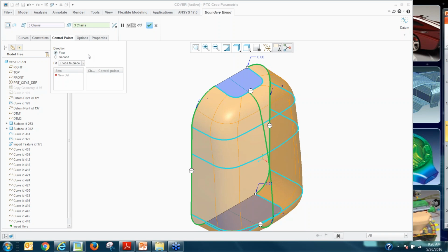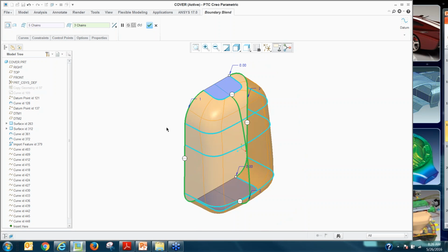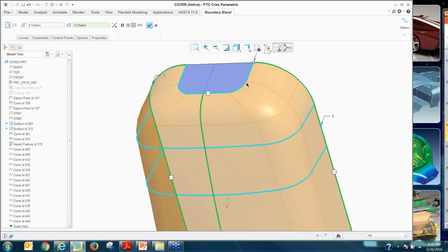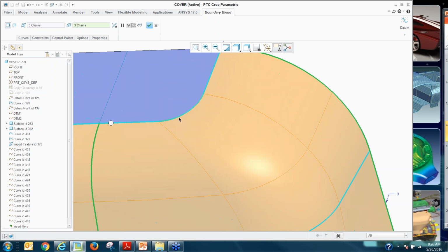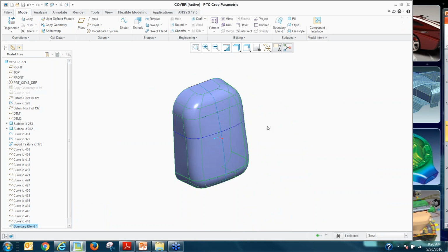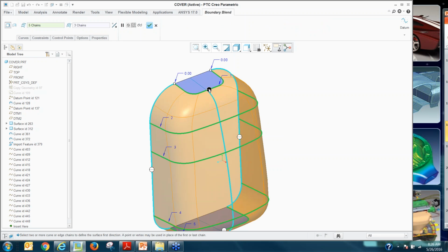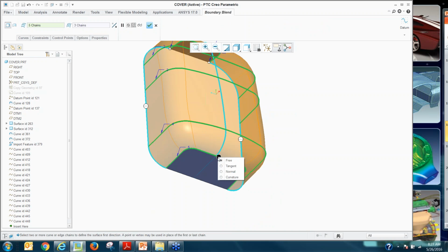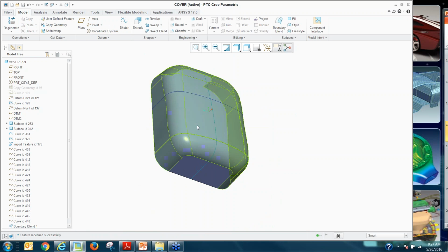So when you do the piece to piece, more often than not, you see how it will try to create the surface patch to the actual vertices through which you created that original curve. Regardless of how many points this might have in the conic, it doesn't matter. So there it is, you got a clean surface there. And of course, you can always redefine, and with these little baseball-like icons, you can add tangency to the existing surface. You can always do that anytime. That's something you want to make sure, that it's tangent to the adjacent surfaces there.